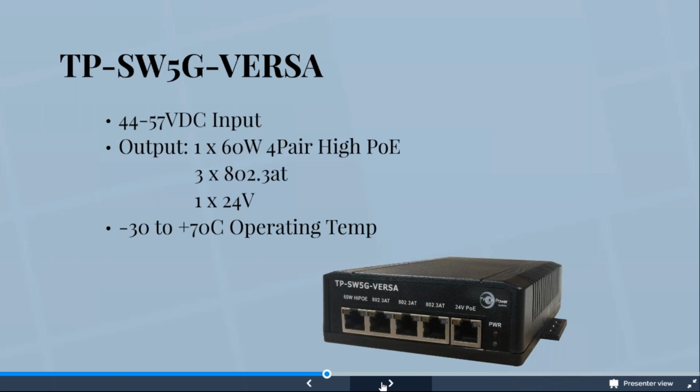and then you would have the different voltage output. We also do have a multi-switch. I didn't highlight that one today. It's not used as much just because of our other switch options, but you can provide dual voltage inputs. So you could have a wire terminal input of 24 volt to get 24 volt off of 2 ports, and then you can have a 48 volt in and have a 48 volt output. So hopefully that answers the question. Most of these devices will just require a 1 voltage input, and then the switch will provide the power needed based on the type of switch that it is.